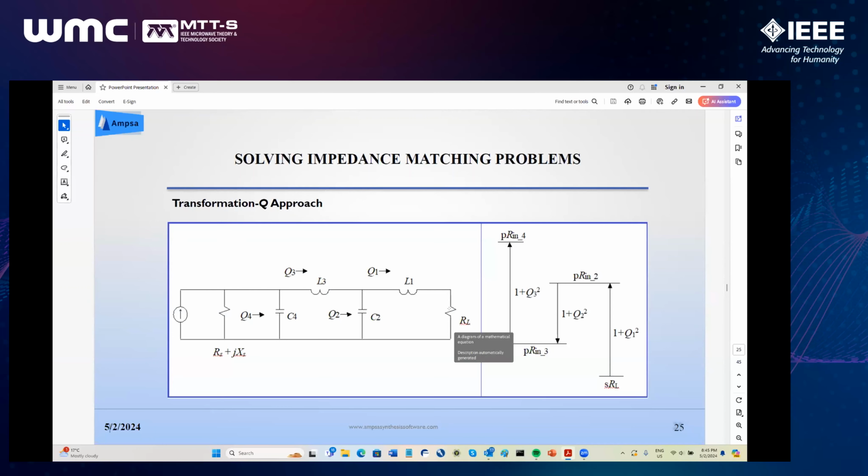So basically, if I look at what is happening in a matching network, there's a resistance there, there's an omega L there, and that has reactance. Now, that considered as an impedance, R plus J omega L, if I consider that as an admittance, it is a resistance in parallel with the inductor. The Q is the same. So basically, this ratio to that ratio is a Q. It can have a sign. If there's this capacitor, it will be negative sign. So if I look at the parallel combination, that RL has changed. It's not RL anymore. And this is how it works.